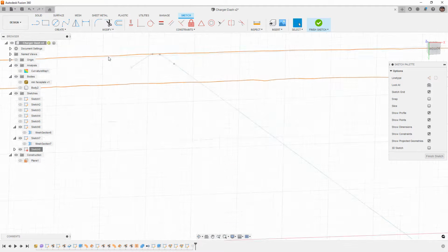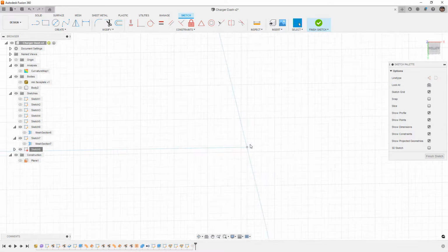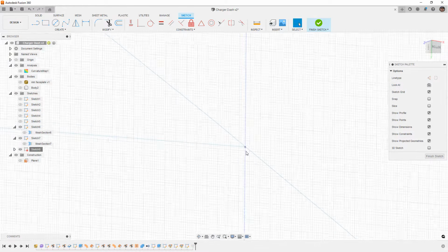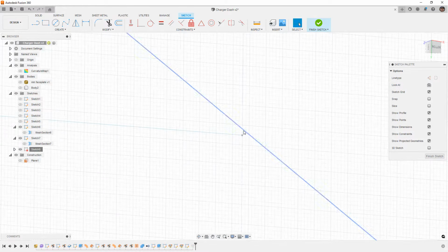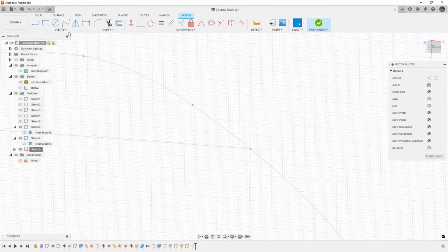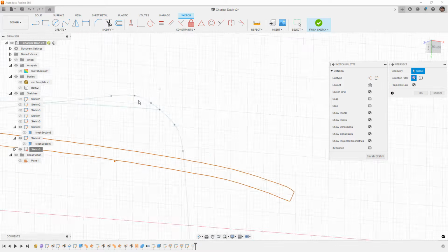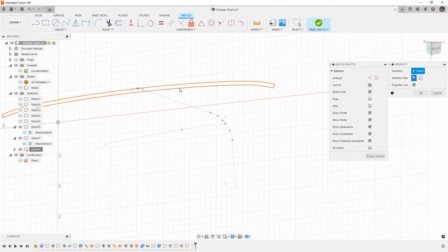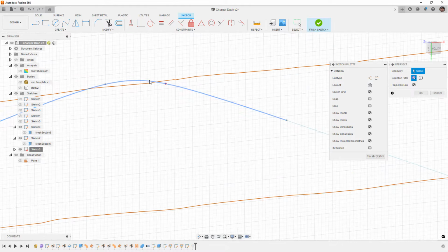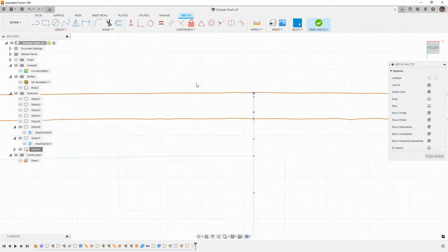And you can see that if you happen to do this a bunch of times, it would get pretty tough. The other thing that we should be mindful of is up here I projected that, but that's not actually the best solution. So you can see that we're not actually hitting that edge. One thing that you can do is you can go to Create, Project, Include, and Intersect, and you can figure out where this curve, whichever curve is closest, is intersecting that sketch, and then it'll give us a point to deal with. So we need to go back and fix that other one.